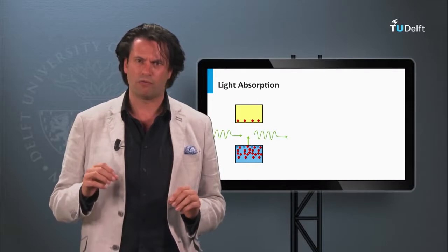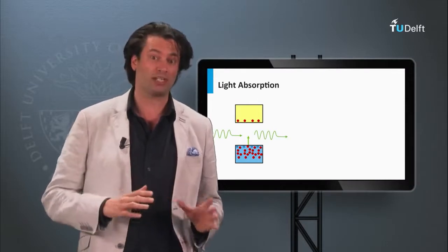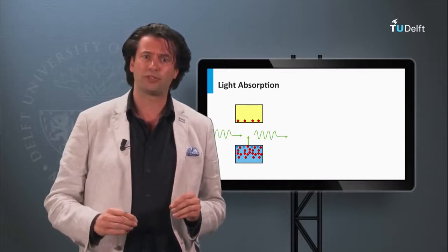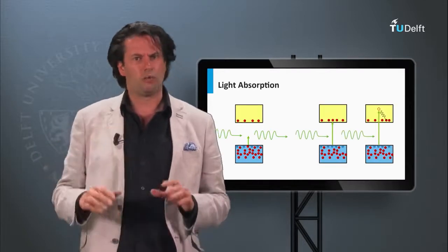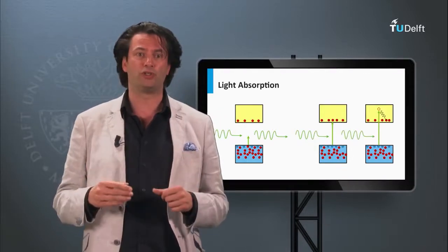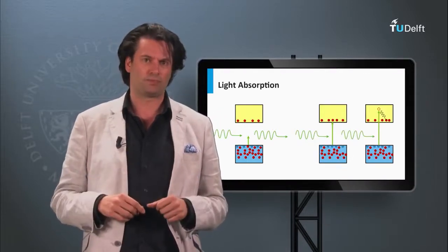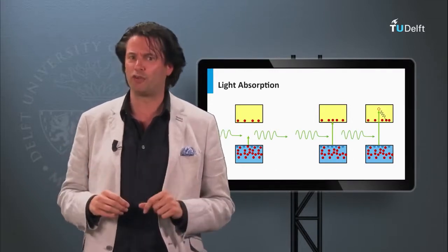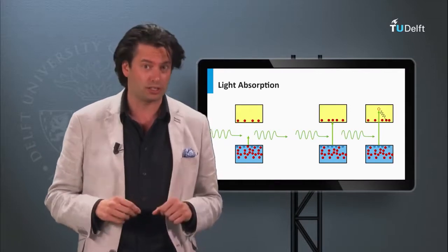We know that when the energy of a photon is smaller than the bandgap, it's lacking the energy to excite an electron to the conduction band. When the energy is larger than the bandgap, absorption of the photon results in a mobile electron and hole. Let's see how the bandgap affects the open circuit voltage and short circuit current density.